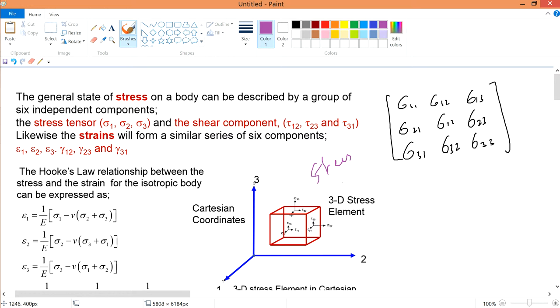But however, we are keen to look at the strain because there is a requirement of the strain: how much strain can be allowed before it cracks. So we're going to translate this in terms of strains, as you can see. These are all your strains, and your shear strains are all your gammas over here. So it's the same thing, I'll write as gamma, like that, and over here I'll write this.